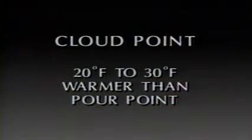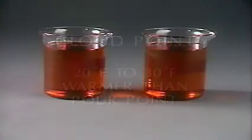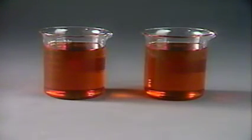Cold weather also causes wax crystals to form in the oil. These crystals can clog filters and strainers and stop the oil from flowing from the tank and supply lines into the burner. This temperature is called cloud point. It is usually 20 to 30 degrees Fahrenheit warmer than the pour point of the oil. Now, let's see how these characteristics affect the ways heating oils are used.